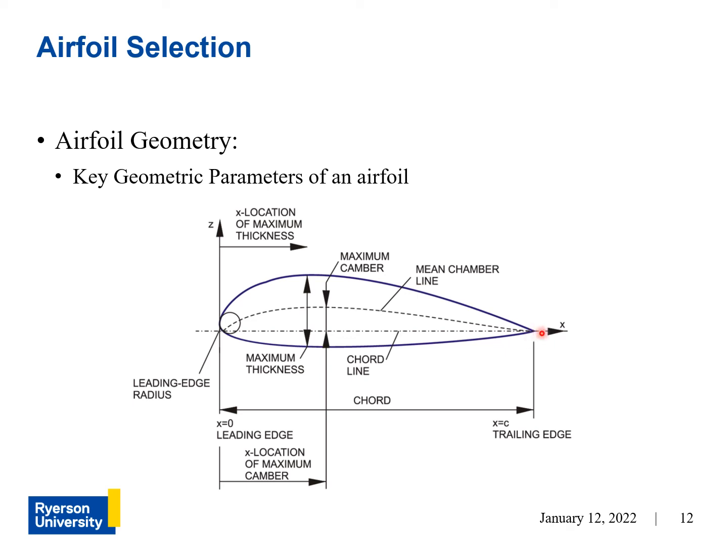It's easier to find the trailing edge point because it's just the sharpest point on the airfoil. So if you find the largest distance, that will be where your leading edge is. Once you know the leading edge, that will be the point at which you reference all other points. In other words, that's your origin point.